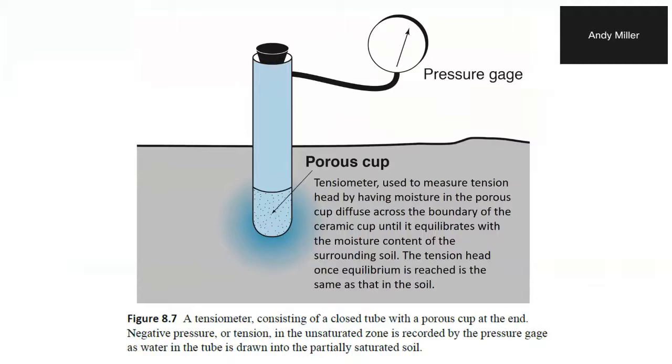You know, if you have those observation points, and if you have enough of them, you can map the distribution of head. We talked about things like piezometer nests for getting different heads at different depths at the same location, and you can track changes over time.